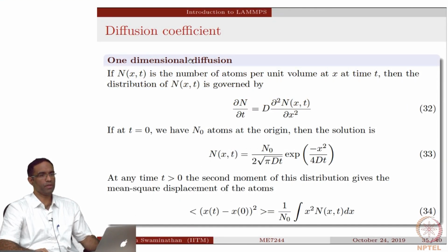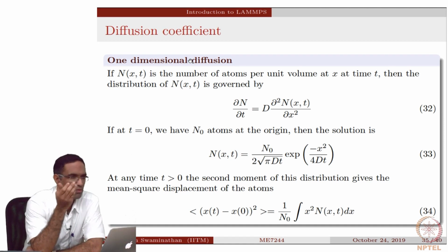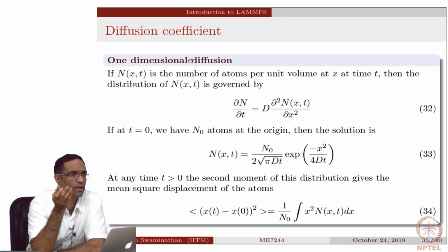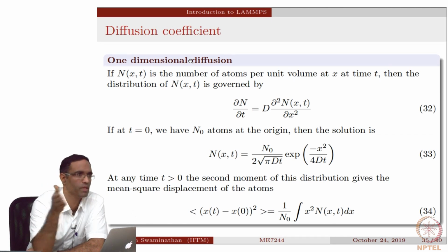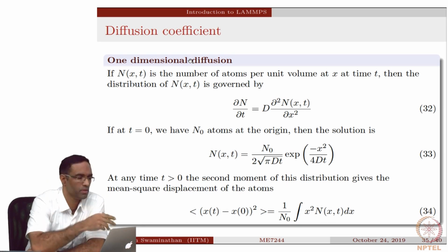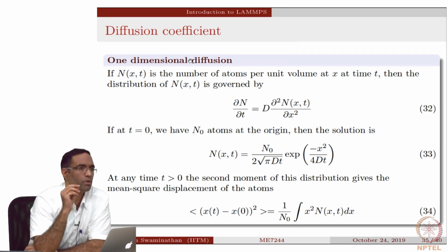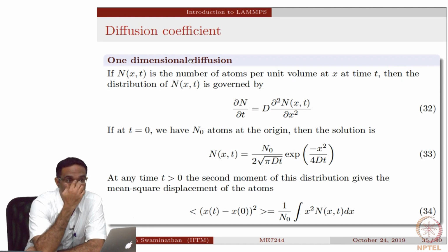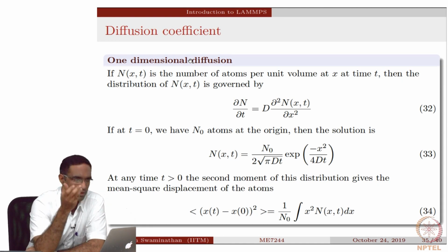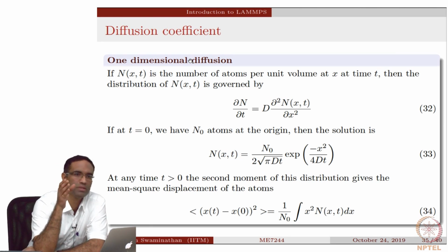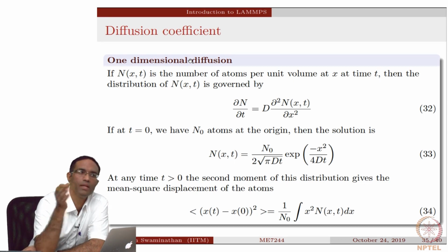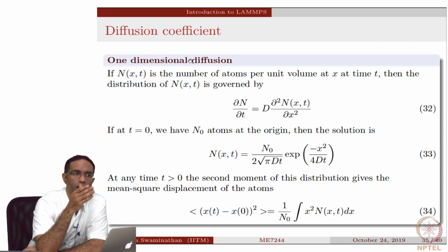We have seen several applications of the fix command and the compute command for calculating, say, radial distribution functions, the velocities and things like that, and then also averaged them over specific time intervals and plotted them in the previous two classes. Another important aspect that we can generally obtain from molecular dynamics simulations is the diffusion coefficient, or the self-diffusion coefficient, of the atoms. This does not require any explicit chemical potential or mass gradient to be provided to the system to see the atoms move.